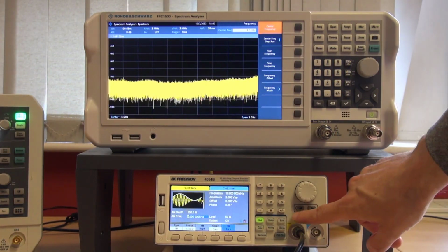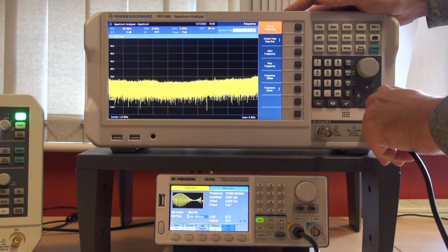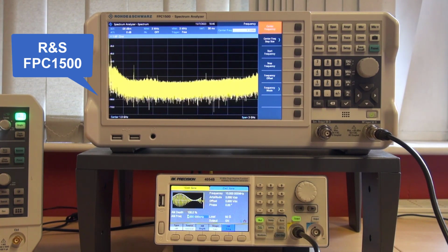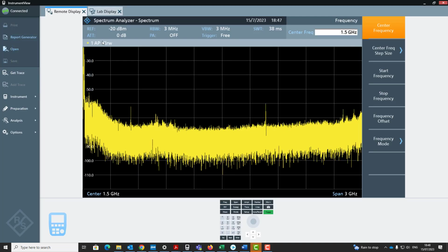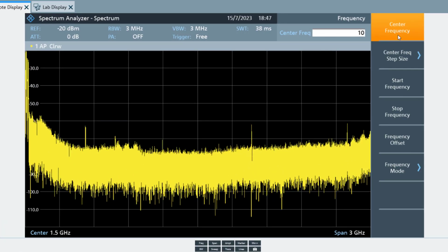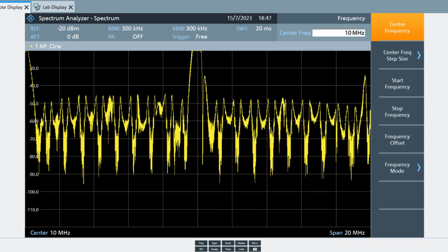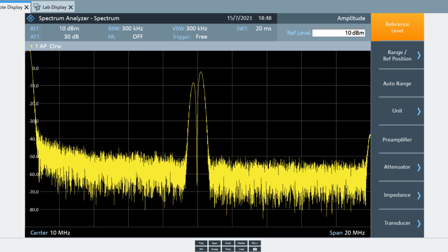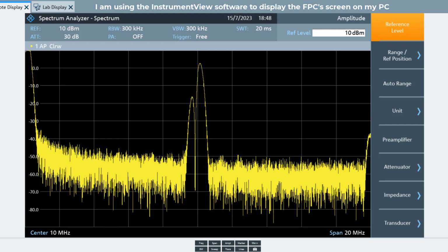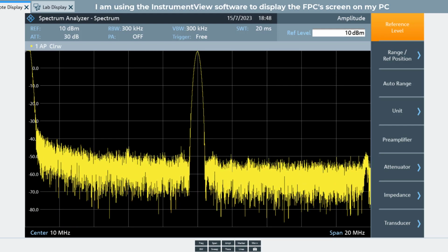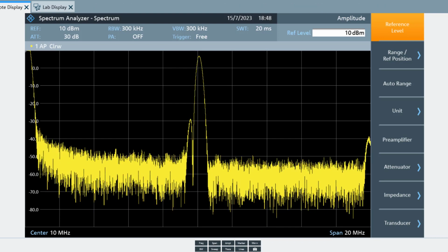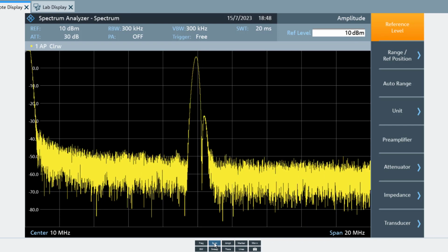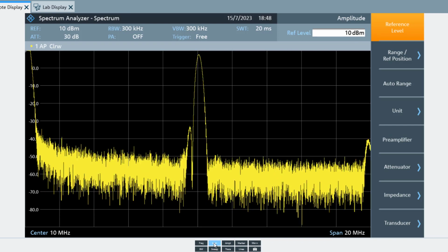Let's now see the frequency content of the signal by means of a spectrum analyzer. We have 20 of these instruments coming to our labs, and they are super useful. Firstly, I need to set the center frequency to that of the carrier, 10 MHz, and change the amplitude reference level so we don't crop our spectral components. At the moment, we can observe significant changes in the spectrum of the signal, and that's not right. It is all to do with the resolution bandwidth of the analyzer, which needs to be set correctly to display the right frequency content of a signal.